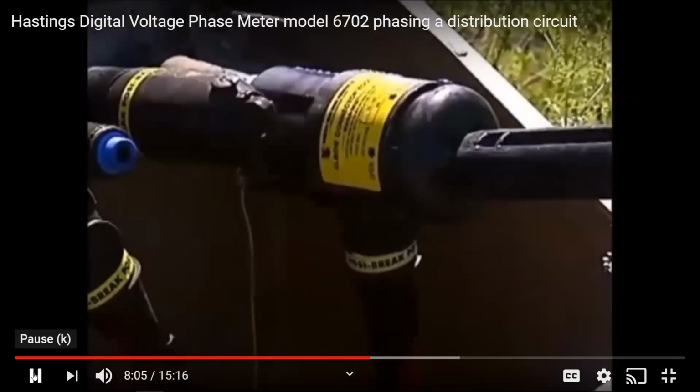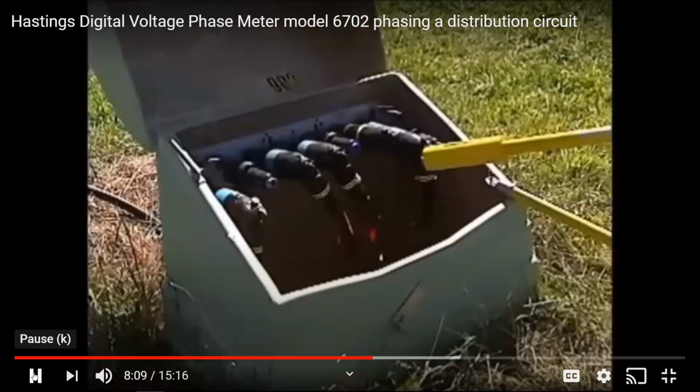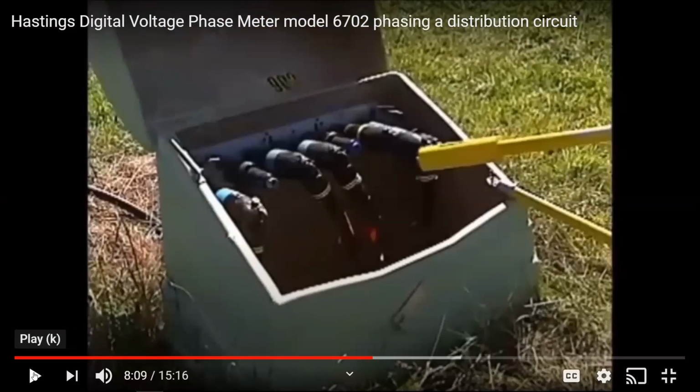Okay, so if you'll go into that. So you'll notice here, and he needs to do this situation in the cabinet. In order for the sticks to high pot, you got to have one energized source free to put the stick on, and you got to have one source on the other side, or one input on the other side where you can put the other stick on to test the conductor. Voltage is required to do the testing with, so that's where he's gathering it from right here. That hot bushing.